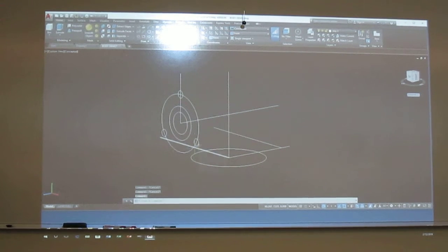Now I'm dealing with my negative shapes. This circle was only for building that. I'm just going to delete it. And let's do an extrude on these guys. 1, 2, 3. They all go the same distance. And they're going at negative. So these are negative 0.375.